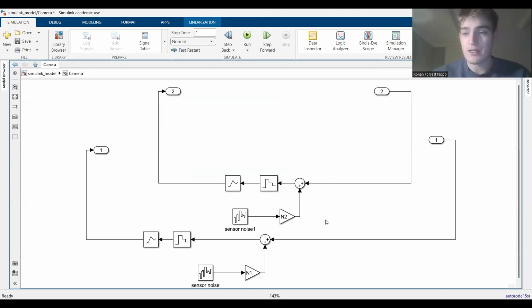That's the culmination of actual noise from the camera sensor, summed with the centroid and the OpenCV algorithm blipping around a bit given the limited resolution of the camera. It's a knob I can turn to see, if the OpenCV output is really noisy and discontinuous, how does that affect the overall output?